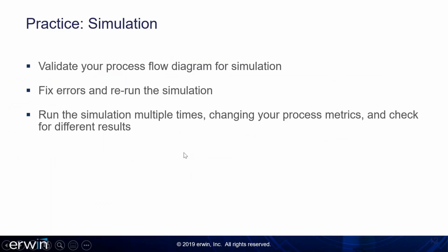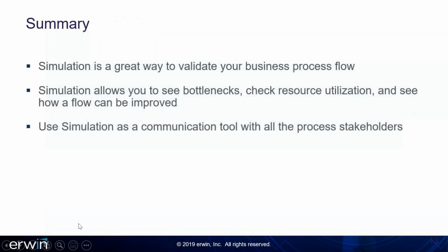So we ran the simulation. I do recommend that you run this on other diagrams, even ones that were not set up in the EA Foundation model. Simply create your own simple process flow, add processes, make sure everything is connected, make sure that there's an event and a result, at least one, and that you have an event frequency and process service time.